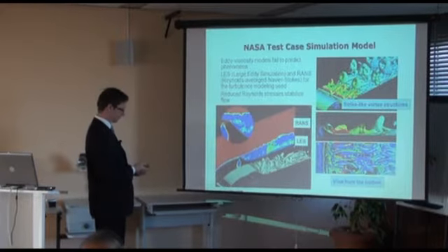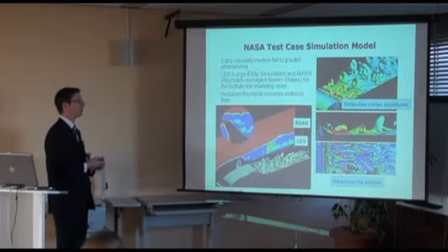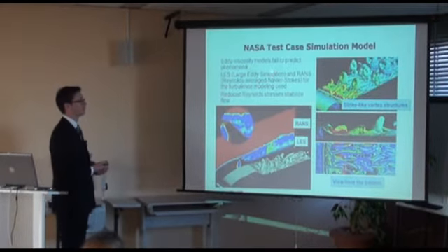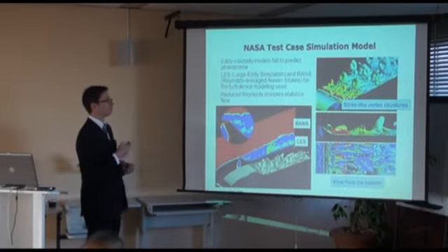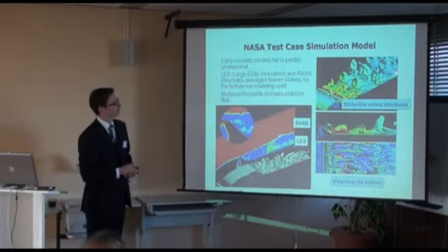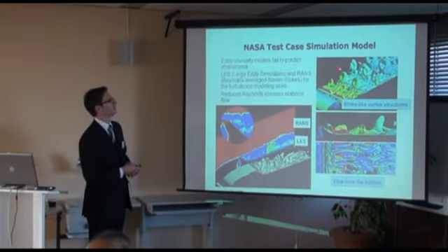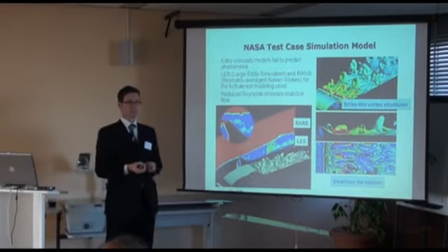Here, you had to apply specially adequate models like LES, large eddy simulation, and RANS, Reynolds-averaged Navier-Stokes, to model these turbulent structures, which are shown here, like streak vortices, a very, very turbulent, very complex flow structure.